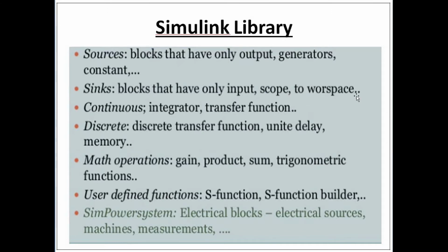And then workspace and continuous signals like integrator, transfer functions. These are continuous signals. Discrete means discrete transfer function. If I require, then you can go to the discrete option, and there you will find the discrete transfer function, delay, unit delay, memory, like this. And math operations, some basic math operations like gain, product, sum, trigonometric functions. These you will find under math operations.